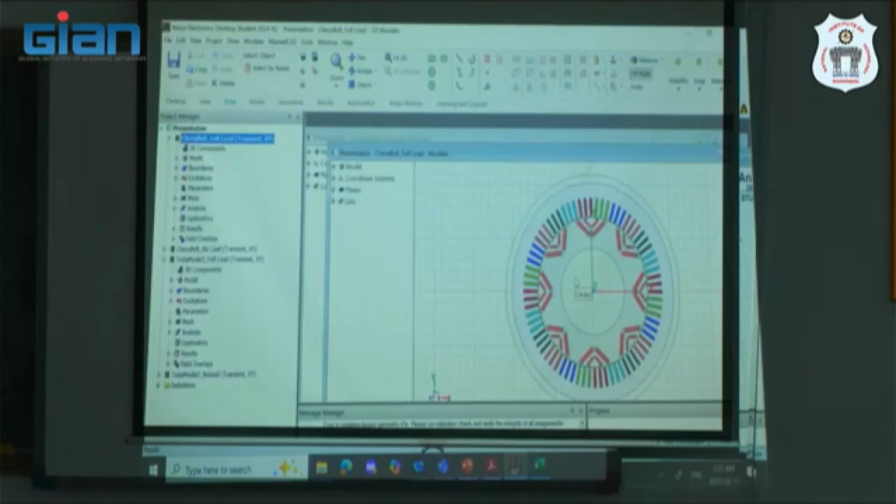One of the analyses we are trying to do is taking these motors, we want to introduce eccentricity in these motors and see how they behave. So we are not creating the design, we are not designing the motors, right? We are using the correct design. We are just introducing a fault of our choice and we are seeing what is the impact on performance. Interestingly, we found some motors have a torque reduction due to eccentricity. So the performance may not always worsen. Cogging torque worsens, but sometimes torque will improve. We have to do more research. All I'm saying is these kind of designs are also possible.